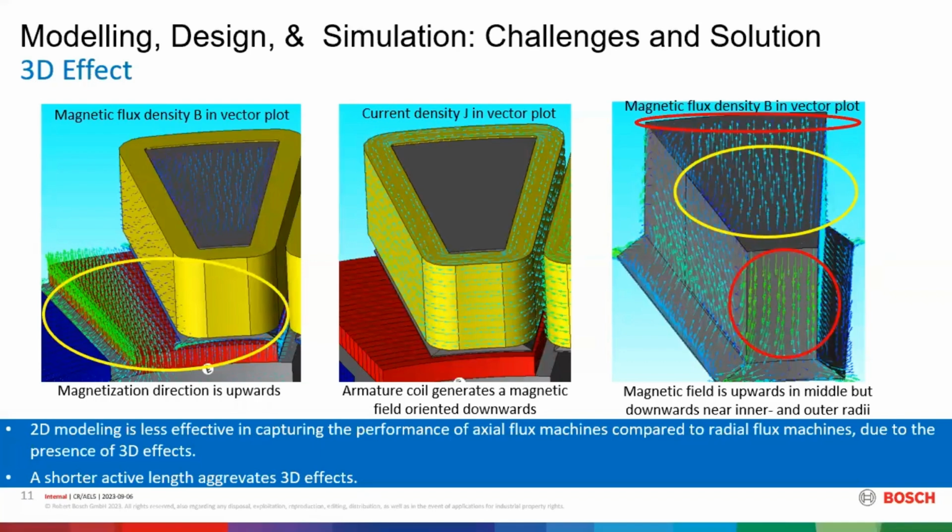And in reality, it's not allowed to go in the radial direction because the material itself is laminated, with a lamination, then some insulation, and then another lamination. And the material in the radial direction might have other BH characteristics than in the circumferential and axial directions. Wait a minute. I have not thought about that, but I think we can discuss it later.